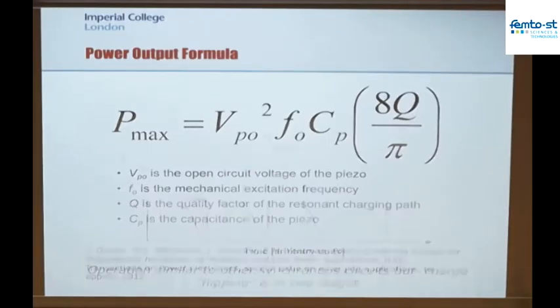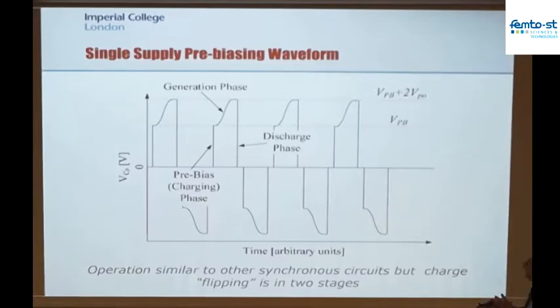So using this type of circuit operation, when you're making your piezoelectric films, one of the things that you need to think about very carefully is that the resistance of those films needs to be as small as possible. So you may well be concerned with maximizing the electrical coupling, maximizing the capacitance. There's various things you might be interested in.